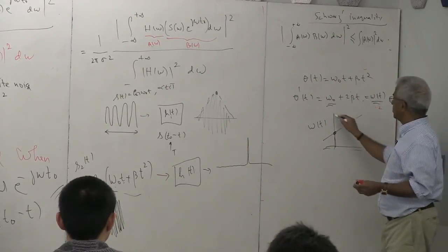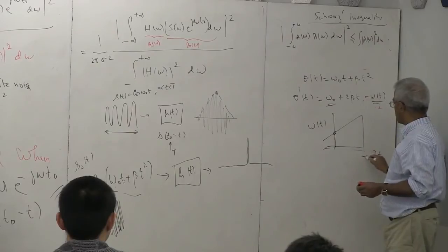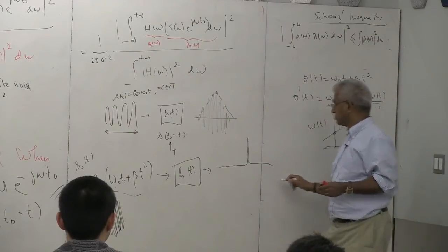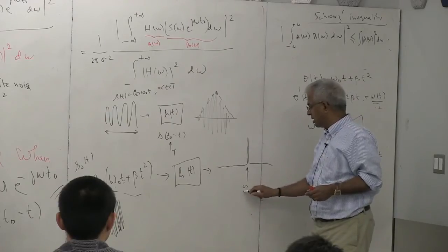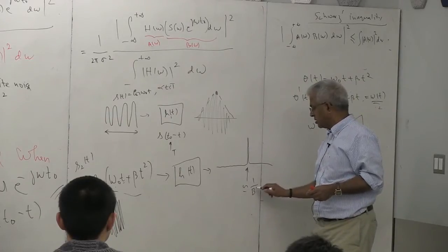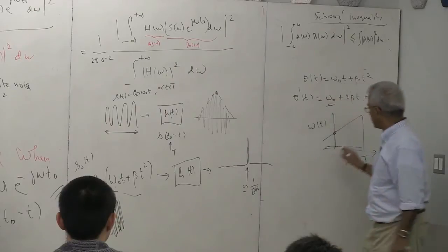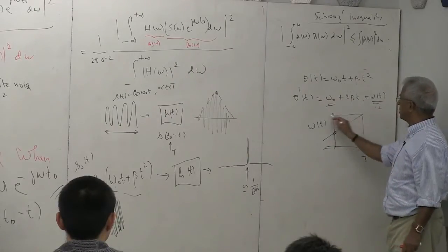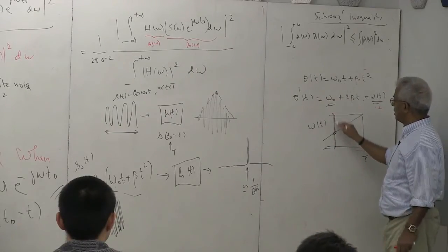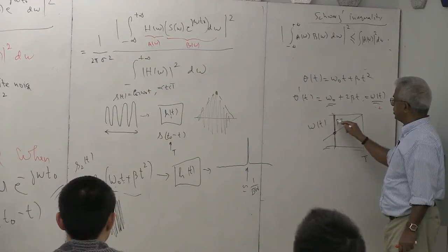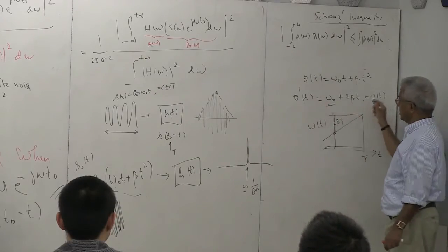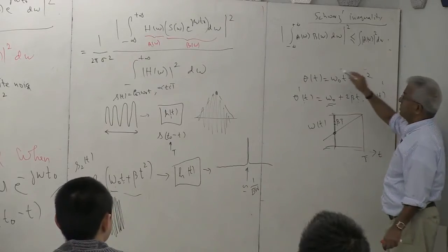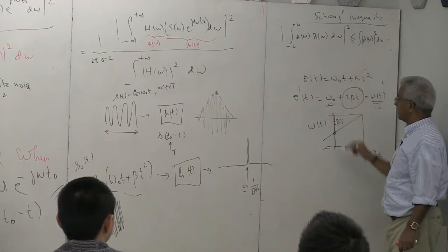The trouble here is if you transmit, you can see that this is inversely proportional to the bandwidth, but the trouble with the bandwidth is, look here. If you transmit for T, this bandwidth is going to be 2 beta T, which you can see from here. This is the instantaneous bandwidth. If T goes from 0 to 2T, this will increase.